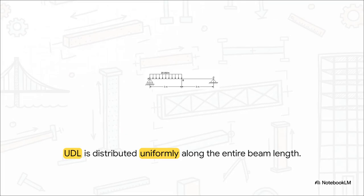But what happens if the weight isn't cleanly concentrated in one place? This is a uniformly distributed load, or a UDL. It's distributed uniformly along the entire length of the beam. Imagine a thick, perfectly even layer of heavy snow sitting entirely across a flat roof. It's not just one heavy point. It's, say, 20 kilonewtons, pushing down evenly on every single meter of that 3-meter span.